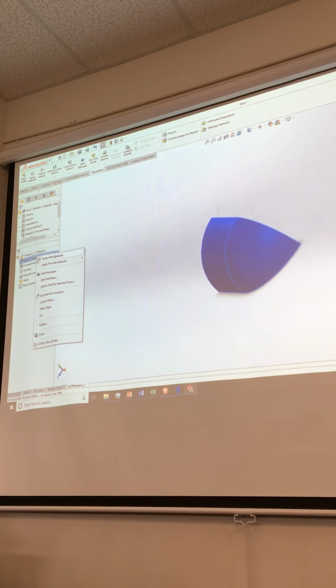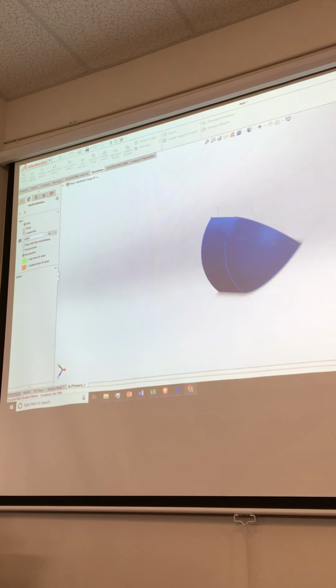I can also edit the definition here. And as part of the definition, it will ask whether it's thin or thick, okay? You can do thick shell analysis with these elements. The thick shell analysis assumes that the stress is not uniform through the material. We basically do a cylindrical analysis. We assume it's a little higher on the inside than it is on the outside, a non-uniform stress distribution through the cross section. For most of what we do, thin shell analysis is fine. It's going to get you close enough.